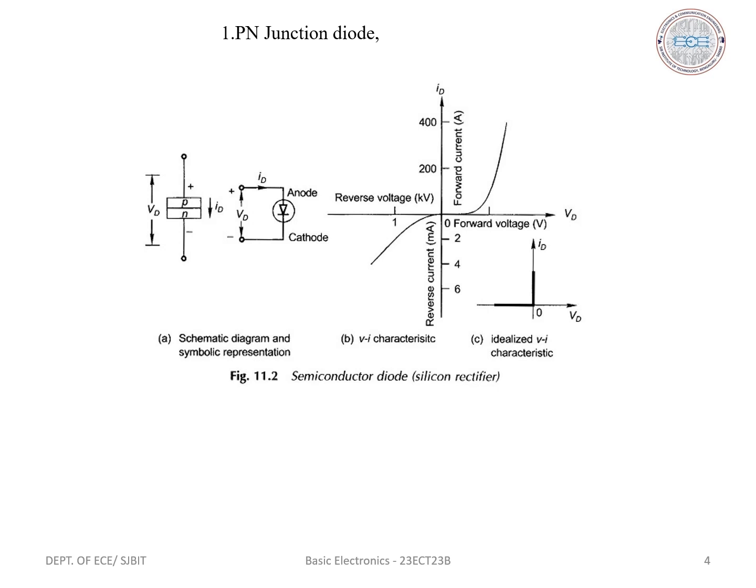The VI characteristics of a PN junction diode is a graph of the voltage across the diode versus the current flowing through it. If a diode is forward biased, then the voltage across it is denoted by Vf and the forward current is If. The forward characteristics are divided into two portions, A to B and B to C.